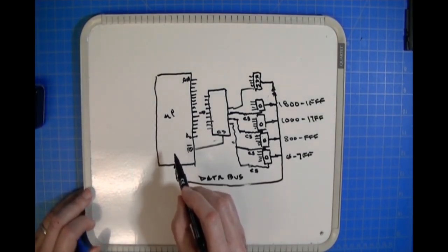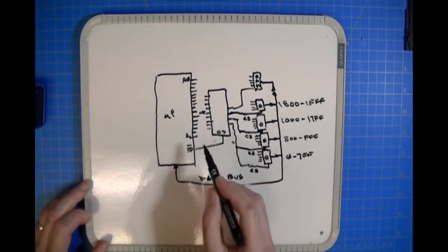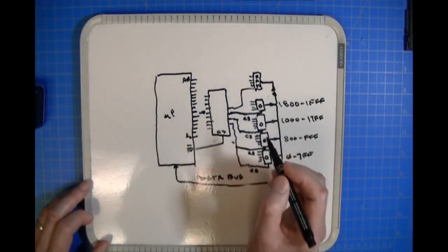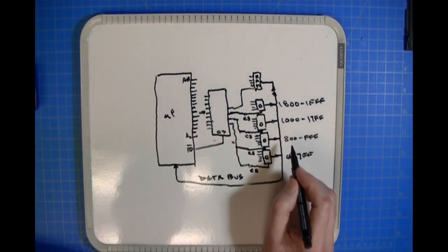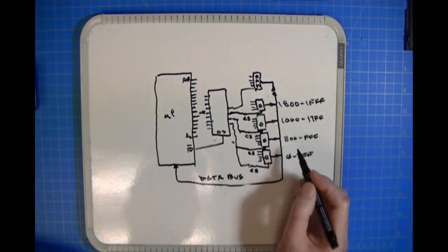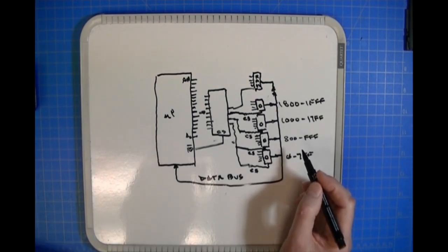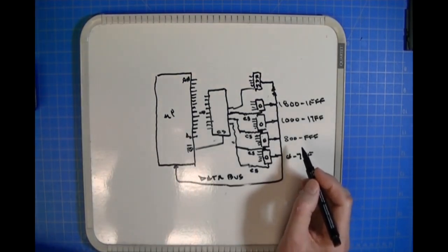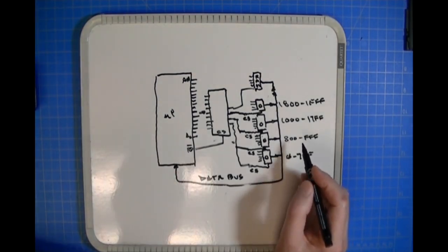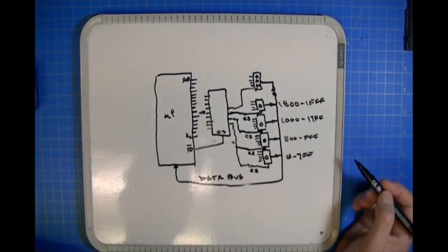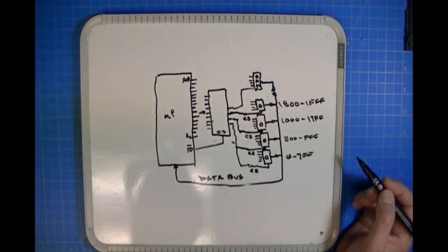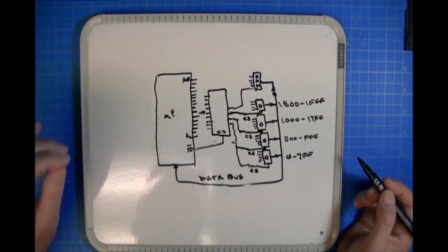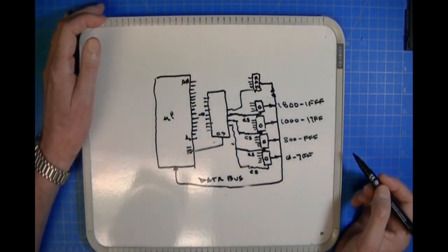Okay, so that's basically why these parts were used, and they were great, okay, because they saved a lot of additional components. But they had one big problem, okay? The big problem was that once you programmed your bipolar PROM, it became a custom part, okay? And one of the things that engineers and purchasing people do not like are custom parts, okay?